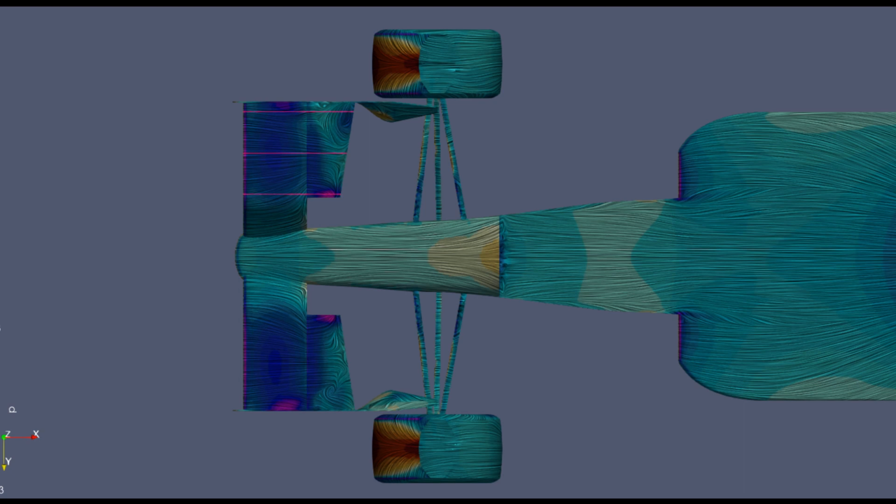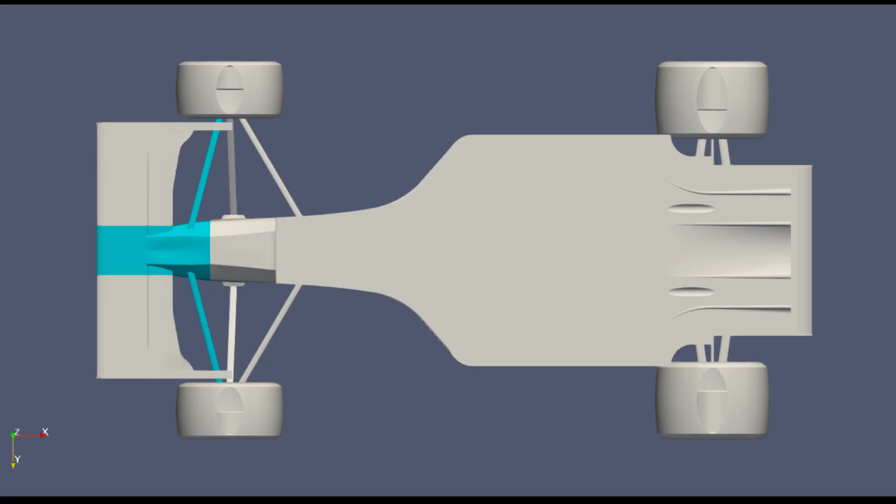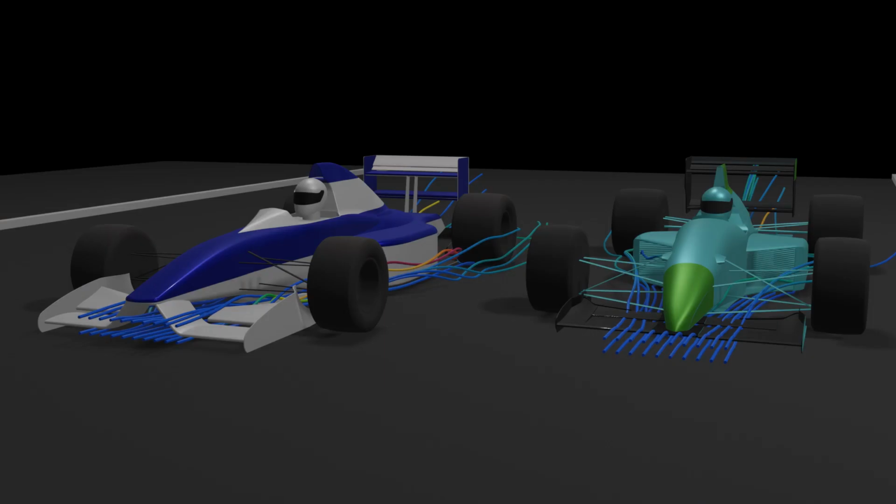The other problem of this solution for the raised nose concept is the lack of wing surface area. The whole middle part of the wing directly connects to the nose, a long way from the ground, and now will contribute very little downforce. This compares to the Leyton House CG901 that had an integrated wing profile under the nose which adds 250 newtons aside from the wings themselves. Tyrrell adopted this integrated design in 1994, before going back to its pioneering concept in 1996. I assume the team lacked the resources to continue the development of the high nose.